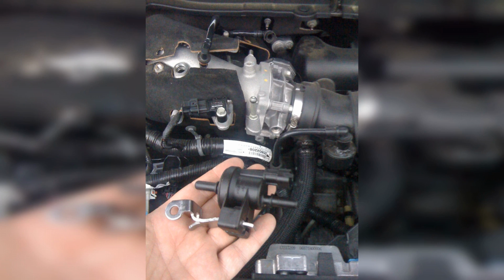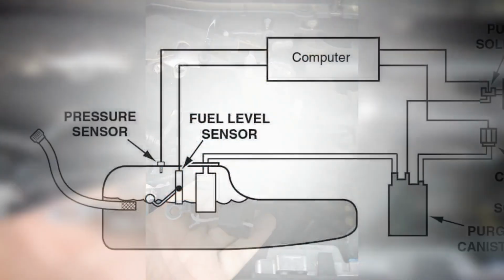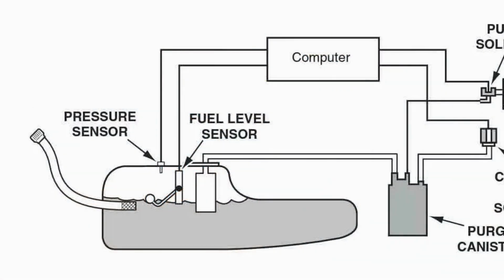As with most OBDI fault codes, there is no quick fix for P0496. There are several possible causes, which means that there are different ways of carrying out the repair depending on the problem that is causing the code to be stored. If you're concerned that your fuel tank pressure sensor is giving erroneous readings, you can have it replaced. While some drivers prefer to leave such repairs to a professional, others prefer to repair their vehicle themselves. This involves a lot of risk, but you could potentially save a lot of money by reducing labor costs.